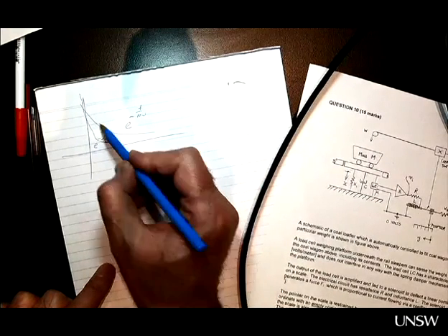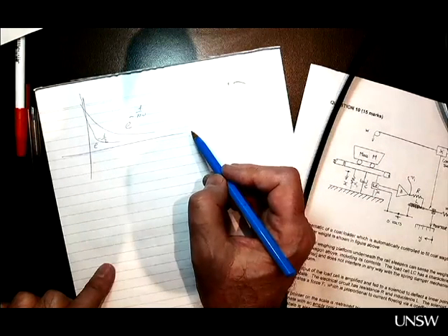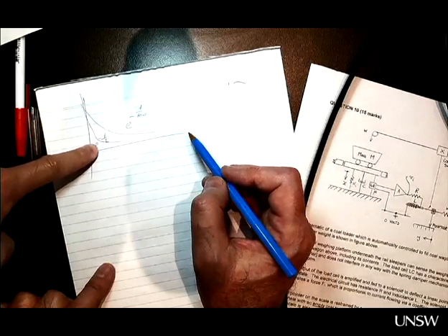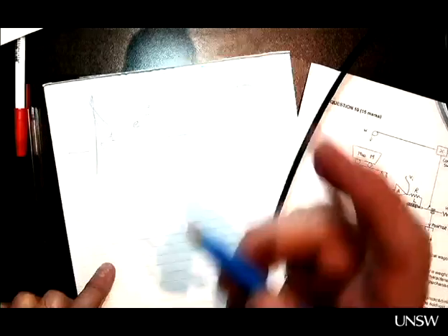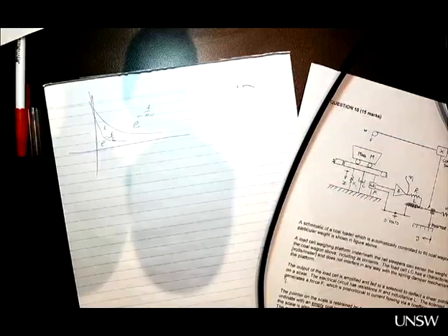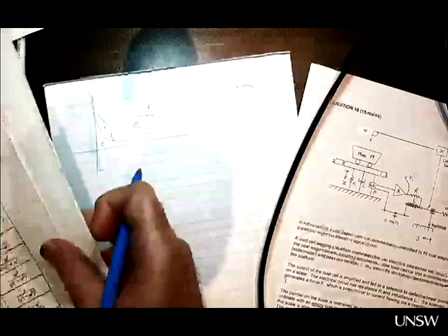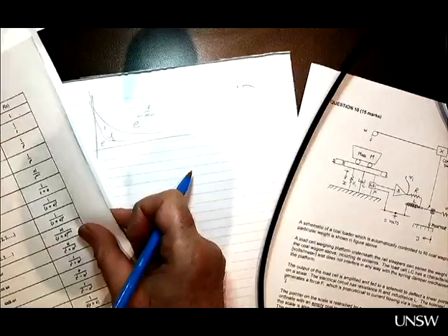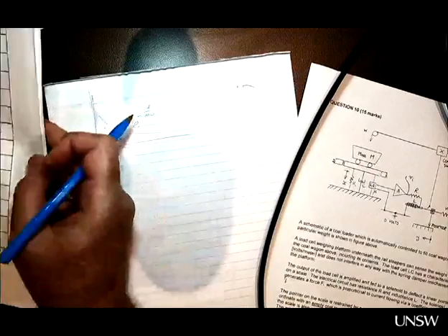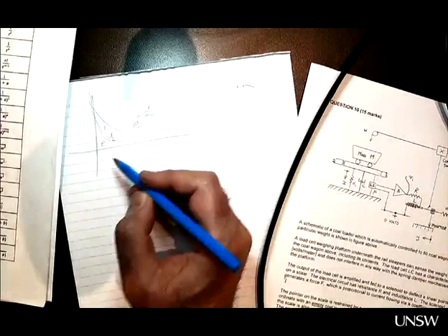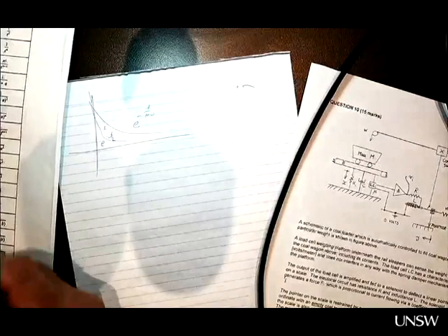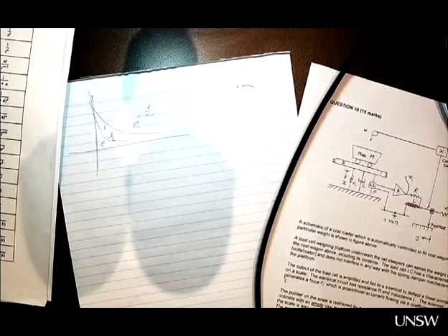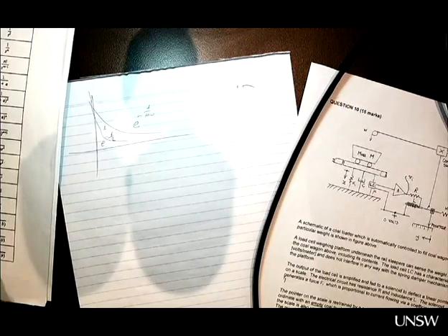You can treat this as a transient system. This is the DC gain, but you're actually adding these two in the response. Sorry, you are subtracting, but anyway, one will disappear quicker, so the other one is staying there. So it is the longer one that dominates the response. If you have five time constants, it is always the slowest one that dominates the response. So the system is as quick as the slowest part of the system.